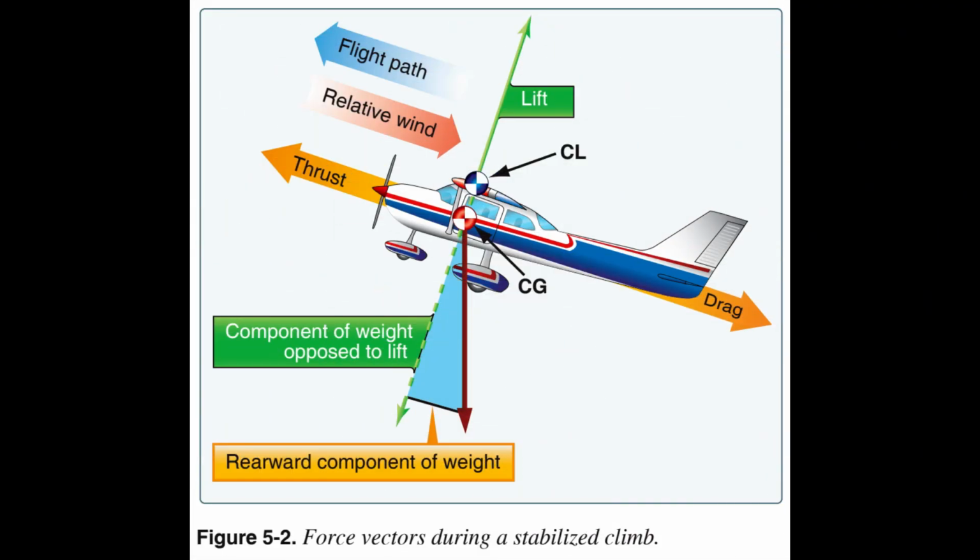This refinement of the old thrust equals drag, lift equals weight formula explains that a portion of thrust is directed upward in climbs and slow flight and acts as if it were lift, while a portion of weight is directed backward opposite to the direction of flight and acts as if it were drag. In slow flight, thrust has an upward component. But because the aircraft is in level flight, weight does not contribute to drag. Figure 5.2.